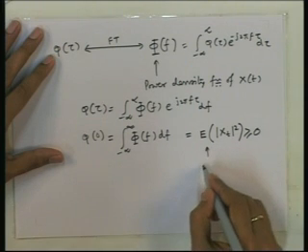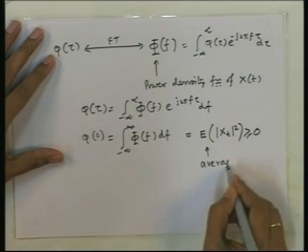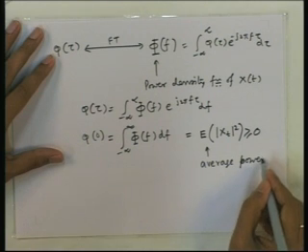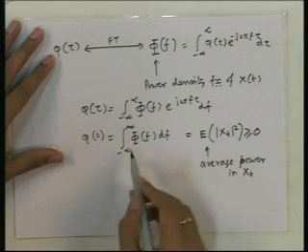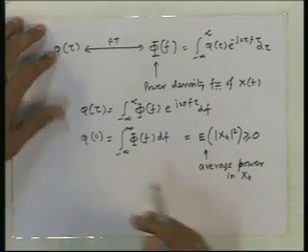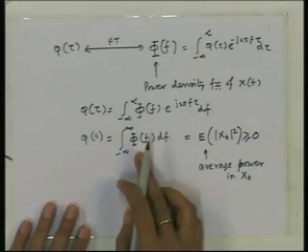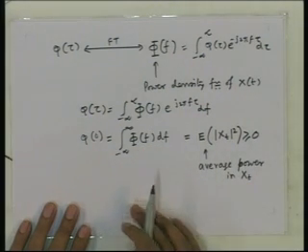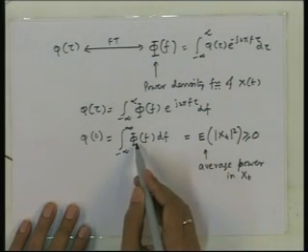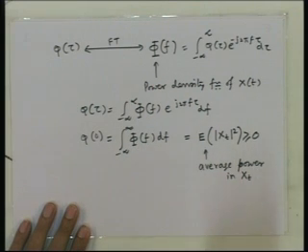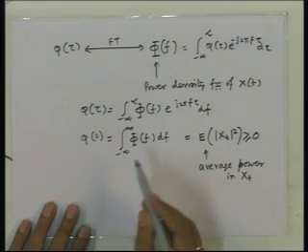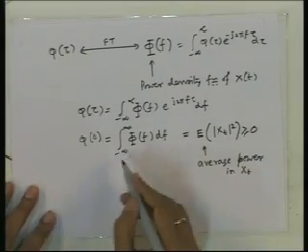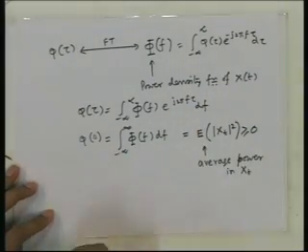So, the area under this power spectral density function is the average power in xt. This function gives you how much average power of xt is there in what frequency. That is why this is the power spectral density, the power density spectrum.